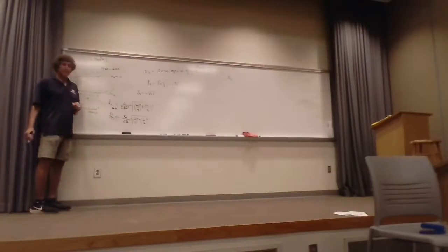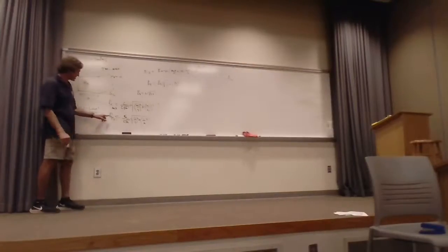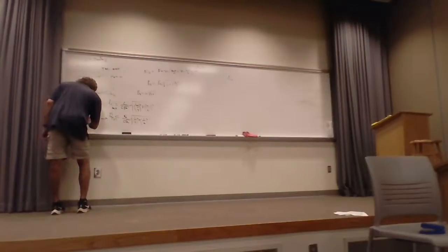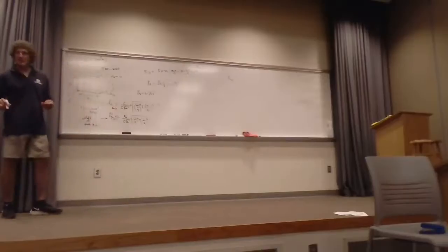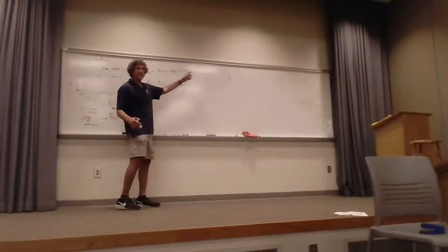So is that not just essentially the cutoff frequency? Like, what is the mode? Yeah, that is the cutoff. The C means cutoff frequency of the lowest. Sorry, if I didn't make that clear. Cutoff of mode M, N. Now it's the same cutoff frequency if we're in the TE mode. You'll see that. So what is mode? What do you mean? That's the value of M and N.